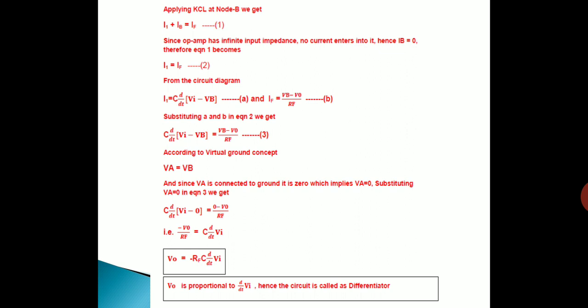Almost the derivation is the same as that of the inverting op amp circuit which we have derived. Equation 1 is the same. Equation 2 is the same. Now we have to write what current I1 and current IF are. If you recall, in the inverting op amp circuit, we wrote current I1 as the current through resistance R1 and current IF as the current through resistor RF. So here current I1 is the current through the capacitor C, and current IF is, as usual, the current through the resistor RF.